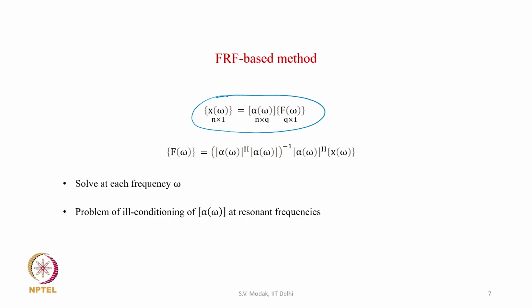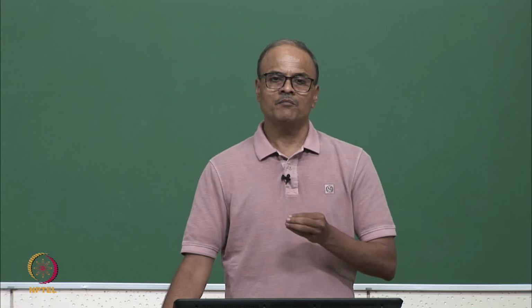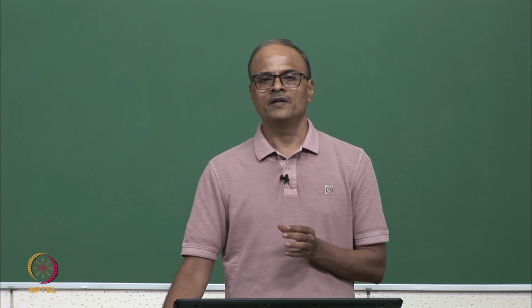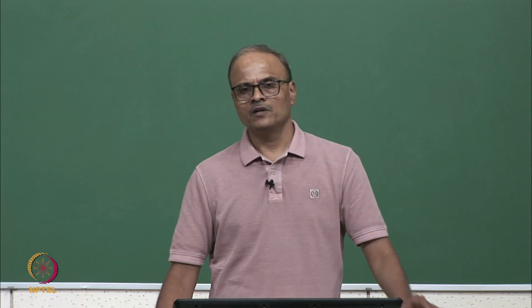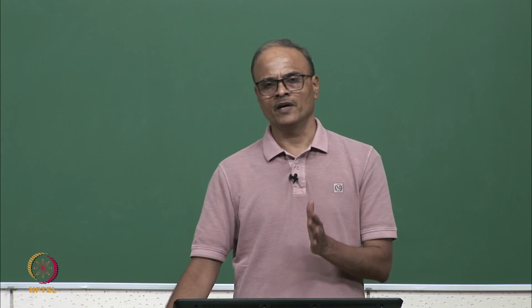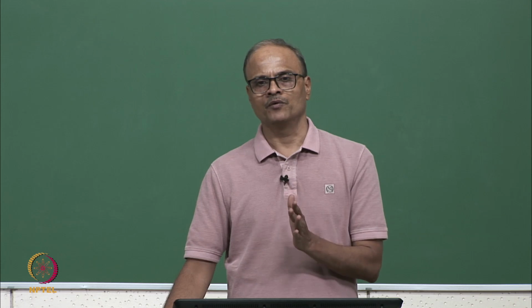This estimation process may also face problems due to ill conditioning of the system of equations which are to be solved, and the ill conditioning may occur because of the ill conditioning of alpha. This alpha may become ill conditioned at resonant frequencies. When omega matches or coincides with any of the resonant frequencies omega m, then the FRF will be dominated by that particular mode.